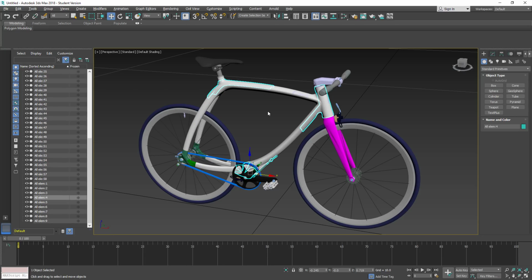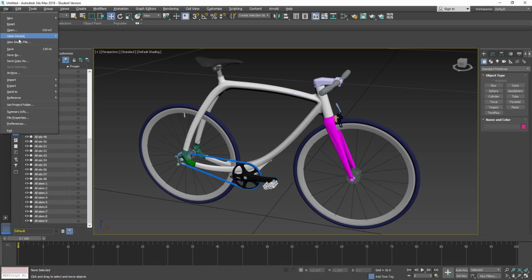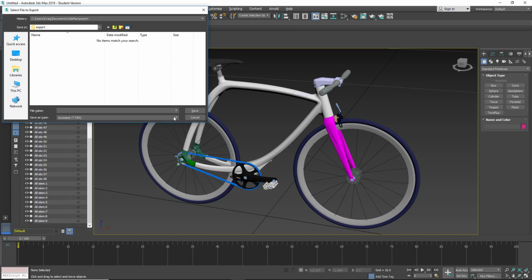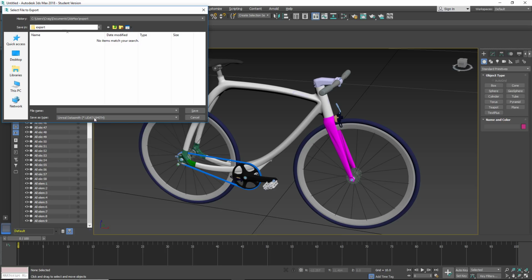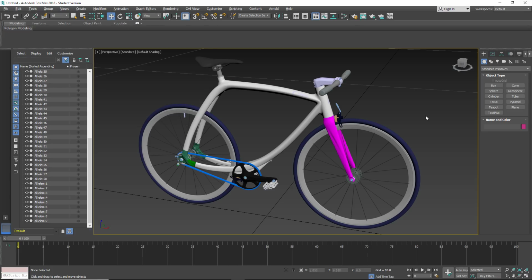The way this works is that we would simply select a component of our CAD data, for example, or we could select the entire scene for that matter. I could do that here. I'm just going to show where it exists, because I'm running the plugin. I'd go to Export, and come down into Save as Type. This is where I'd find the Unreal Datasmith, or .udatasmith, file format, which I could click and begin to write out all of this data. It's going to send that out and write it into its own Datasmith format.